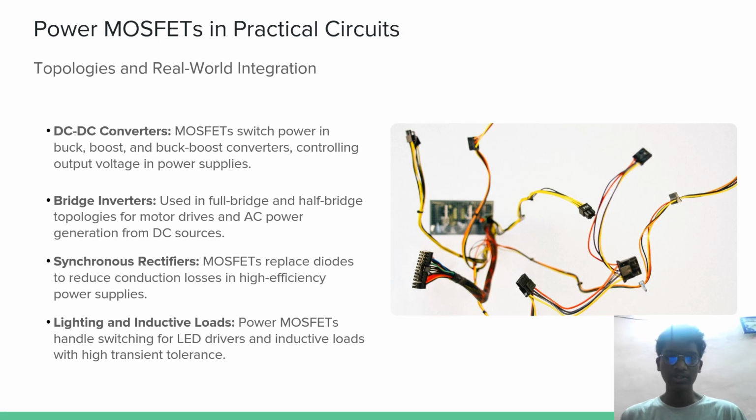Bridge inverters: used in full bridge and half bridge topologies for motor drivers and AC power generation from a DC source. Synchronous rectifiers: MOSFETs replace diodes to reduce conduction losses in high efficiency power supplies. Lighting and inductive loads: power MOSFETs handle switching for LED drivers and inductive loads with high transient tolerance.